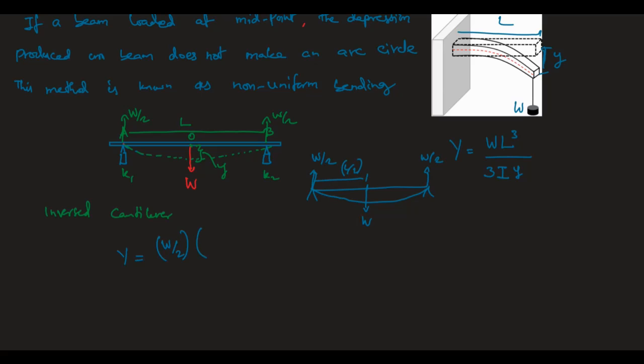So you have to think of L by 2 as the length of the cantilever now. I am going to substitute the values for W and L cube.